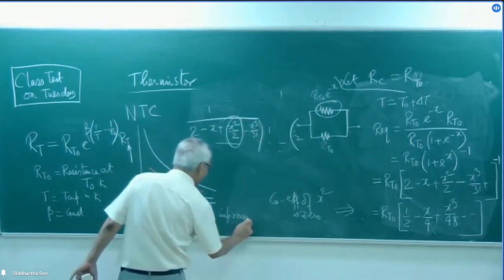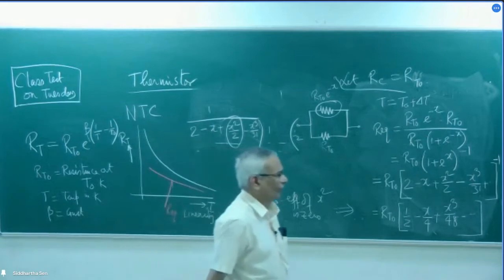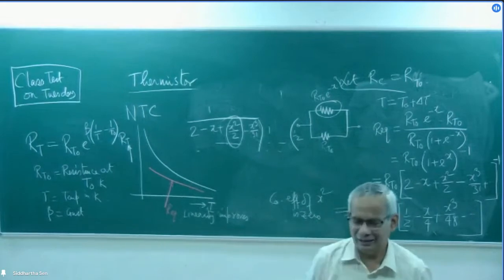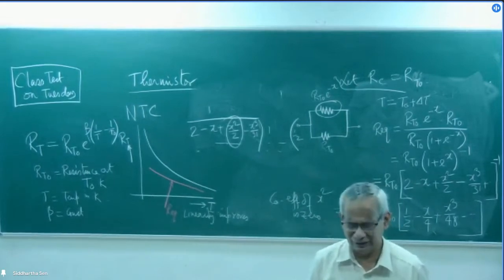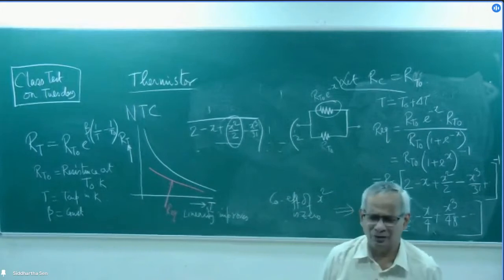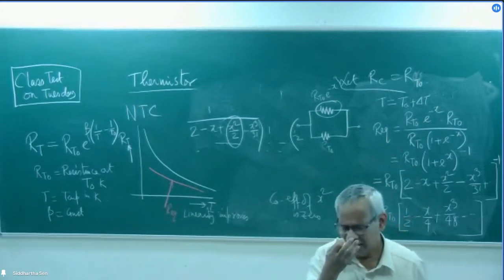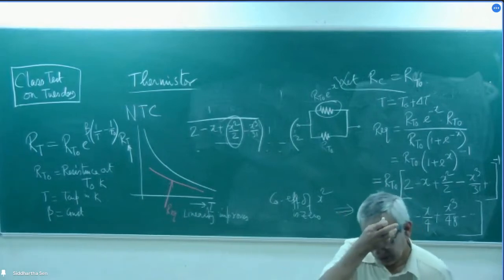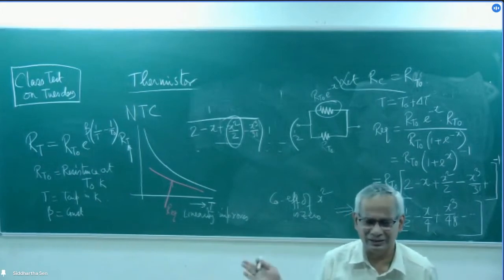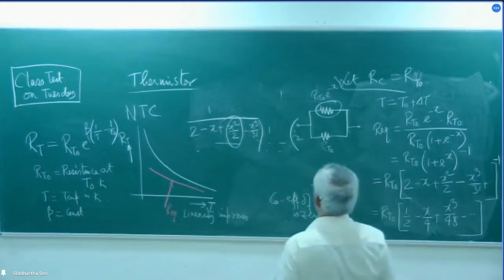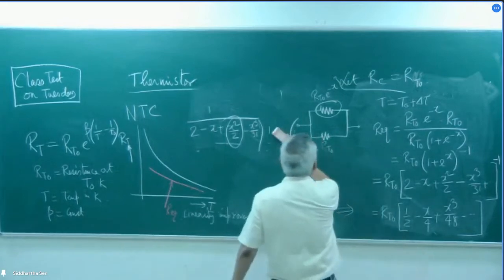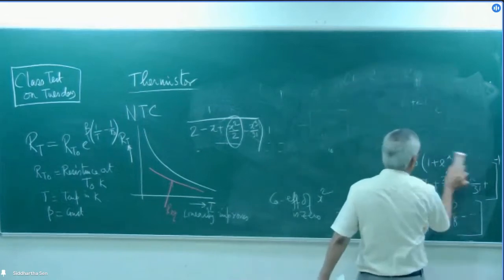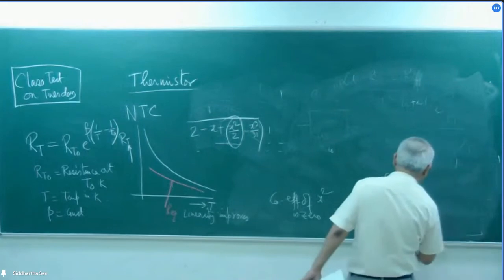So that's the interesting thing of this thermistor characteristic, this exponential characteristic: by putting a parallel resistance, of course, we are sacrificing the sensitivity. In fact, we don't mind because the thermistor has a very high sensitivity. Rather, we want the linearization that can be achieved by this. This is what we calculated by method 1, the parallel resistance.